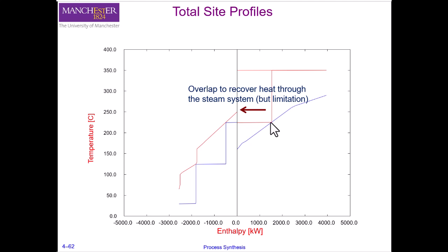And again, where this curve touches the composite curve, there is a whole delta T min difference between the real temperature of the steam and the process temperature of these cold streams that require the heat, which has been shifted by a whole delta T min value.